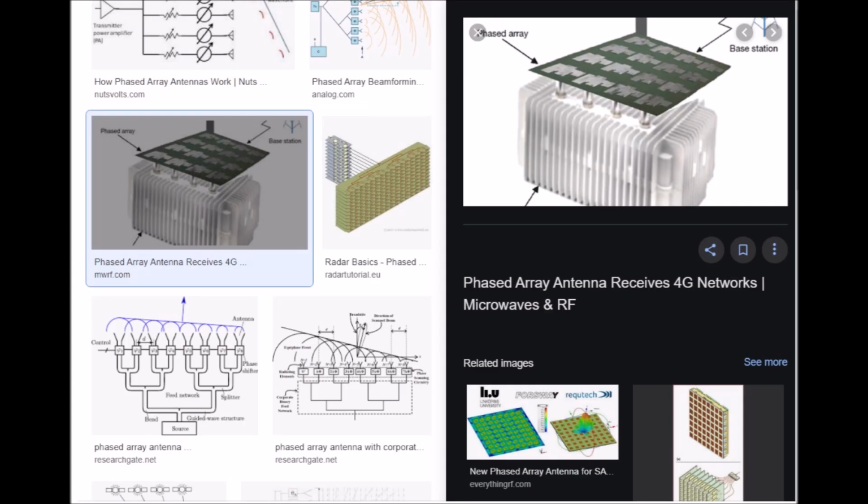A phased array consists of two or more simple antennas which are connected together through an electrical network. This often involves a number of parallel dipole antennas with a certain spacing, depending on the relative phase introduced by the network.